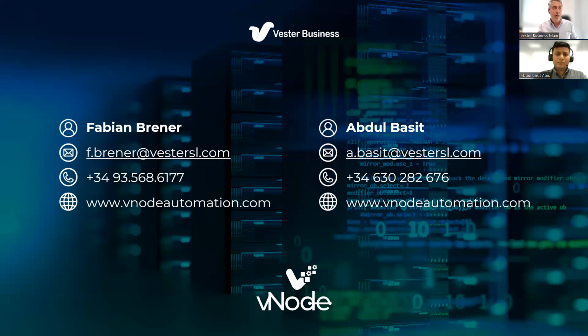In real time, vNode is going to be updating the data inside vNode. Then we have said that vNode, using MQTT in this demo, is uploading the data every 5 seconds. So every 5 seconds, we're going to be publishing the data to the cloud, okay? Because we said 5 seconds. If we say 1 millisecond, it would be 1 millisecond. Of course, 1 millisecond is completely out of reality, but probably 100 milliseconds could be more real, 150, 200 milliseconds, I don't know.